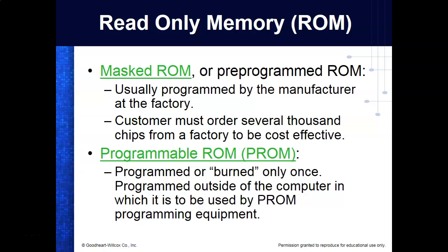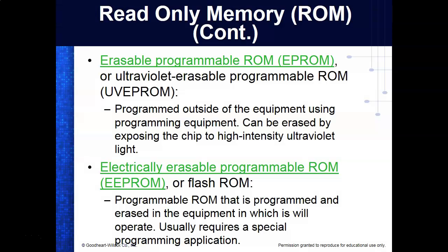Even when we deal with these other ones, now we call it flashing, because the ROMs are flash ROMs now, which are double EEPROMs. So we call it flashing now, but we used the term burn for anything above a mask ROM for years. Programmed outside of the computer in which it is to be used by a PROM programmer. And we've got one of these up in A210. I need to go up there and see if I can handle getting it down to class.